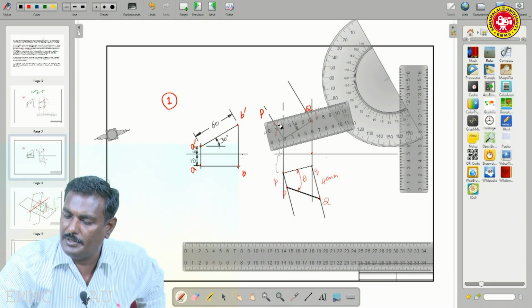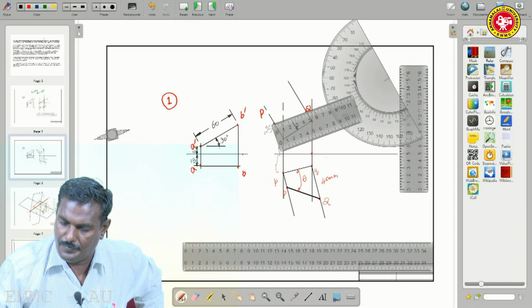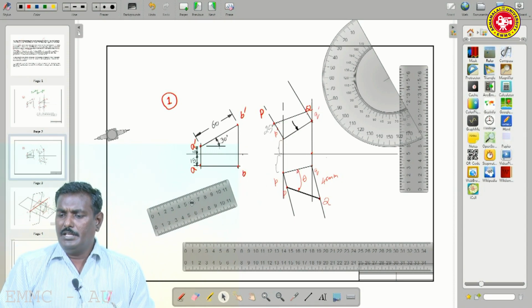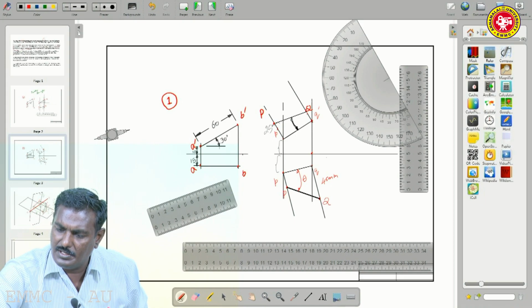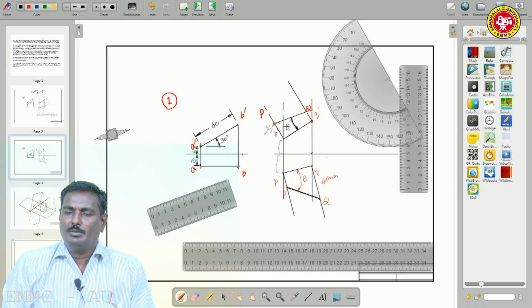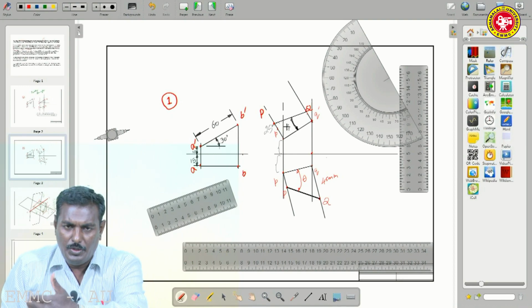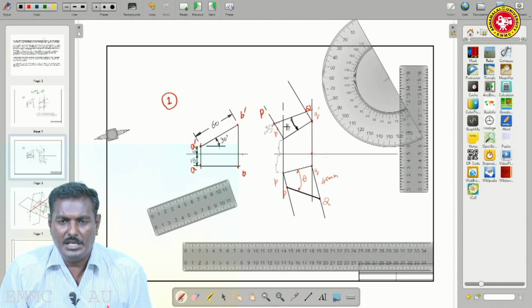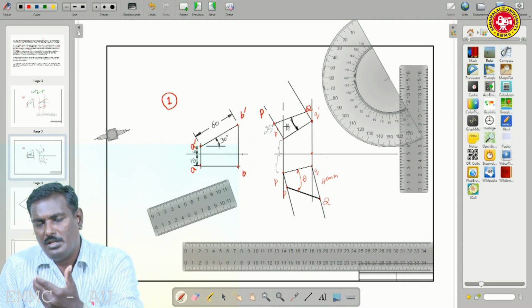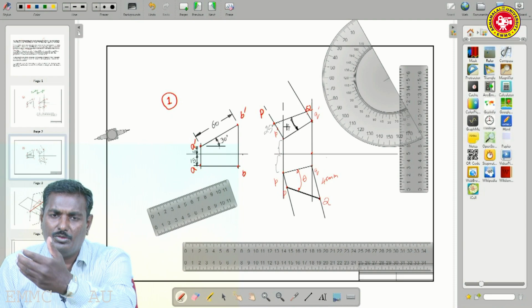Now, draw a line. Yeah, this will give the true length. So, that is the concept. Now these projections, the inclinations give beta. In this way only we are able to obtain the true length and true inclinations. Below you have to draw a guideline and print the true length of the line, the true inclination with respect to the horizontal plane theta, and the true inclination with respect to the vertical plane beta. Whatever values come, you have to write them.